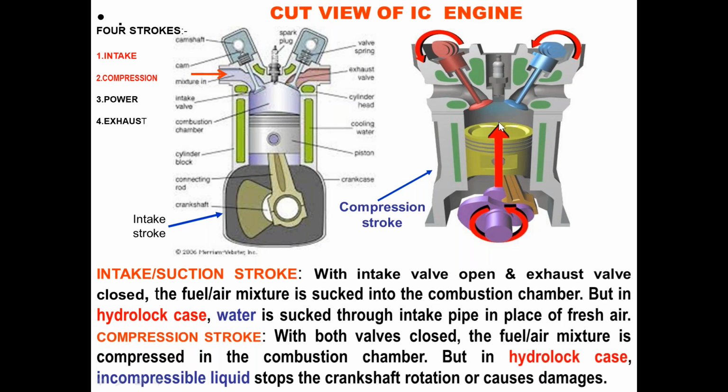Here the fuel air mixture is compressed by the movement of the crankshaft and the upward movement of the piston. But in a HYDROLOCK case, instead of fuel air mixture, there is incompressible liquid, maybe oil, maybe water, which stops the crankshaft rotation and causes damages.